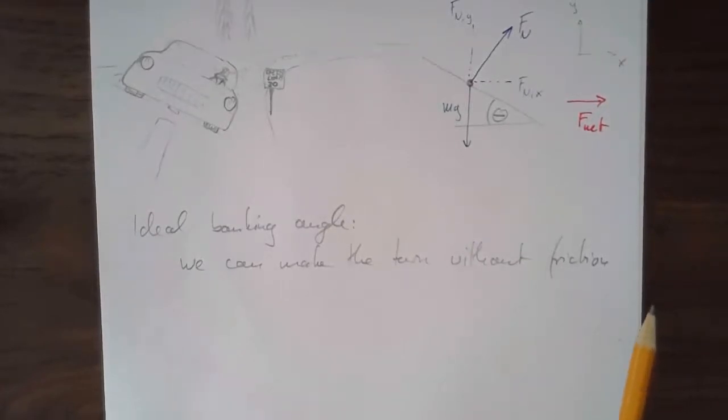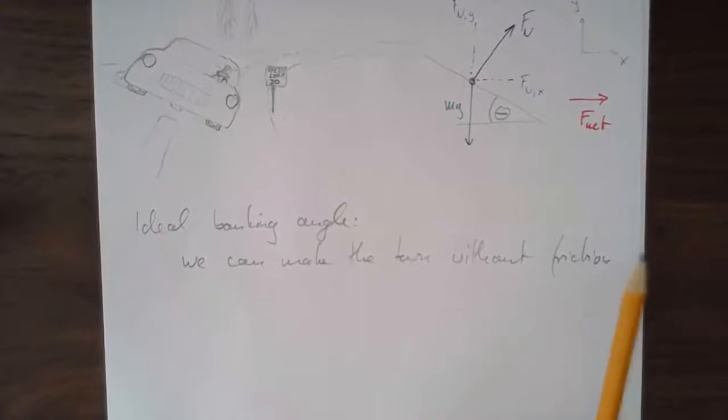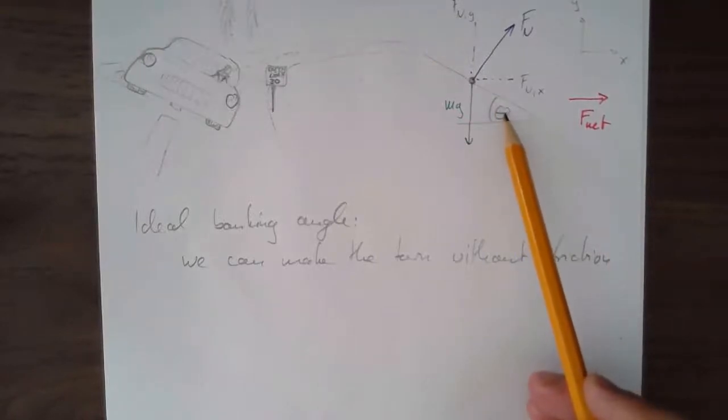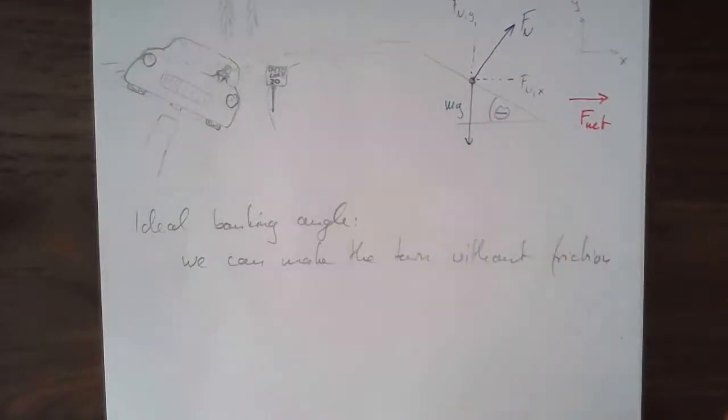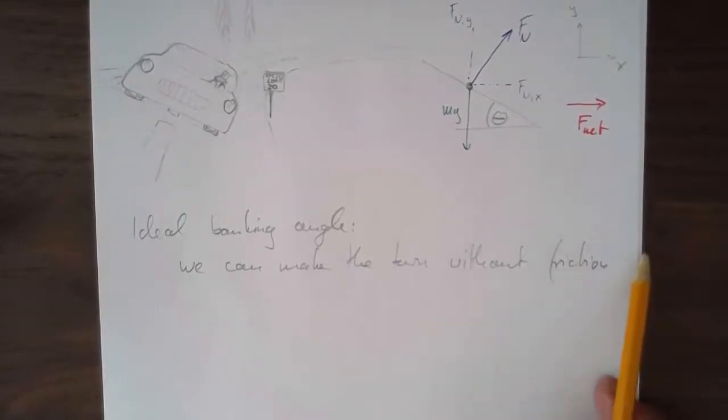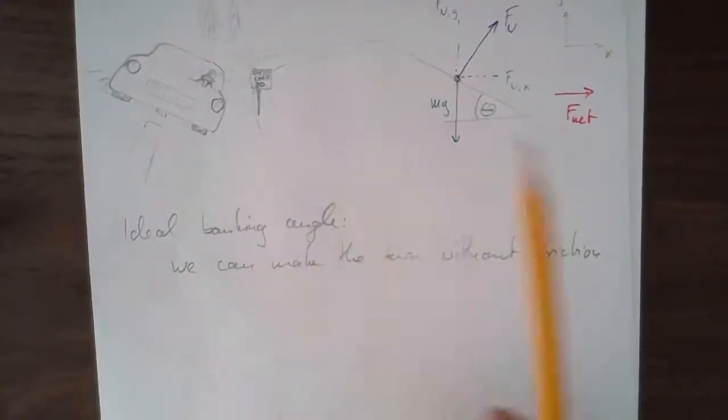You're going to say, well, look, here's a stretch of road, and the cars are going to go, I don't know, let's stick with the 30 meters per second that we had before. Right, so at what angle should I build my road to allow cars to go at that speed? Right, the ideal banking angle depends on the speed of the vehicles going along that stretch.